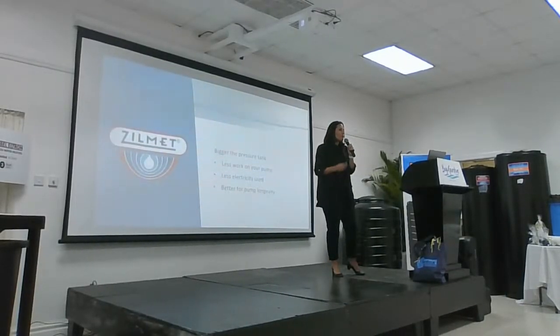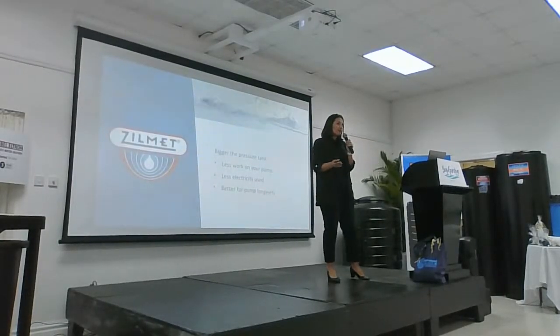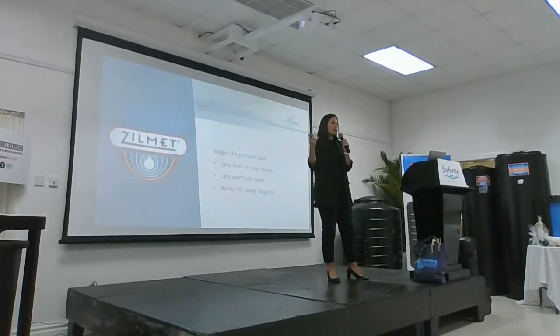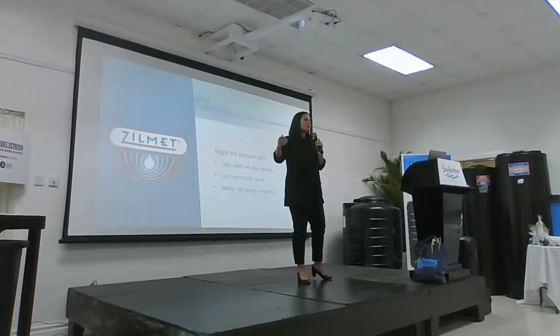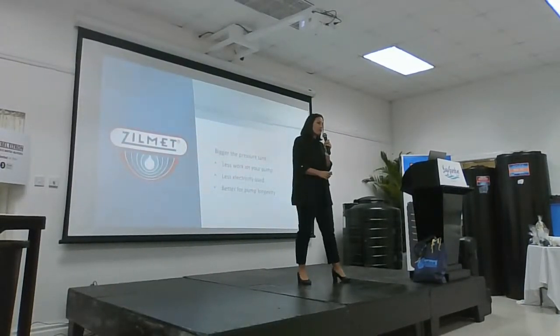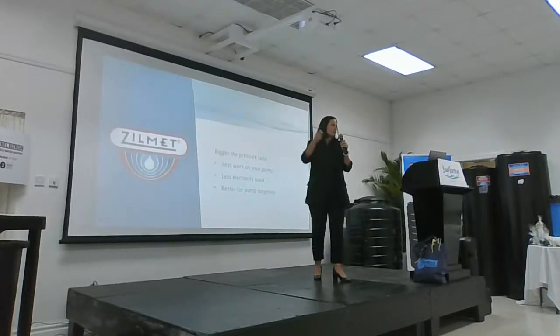With pressure tanks, we always say the bigger the tank, the better. Simply because from a pump manufacturer's point of view, the longer periods that your pump can run is better for your pump. The reason being, it's less work on your pump, it runs more efficiently, and you save cost on electricity because your pump is running better.